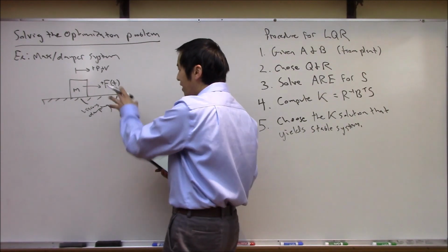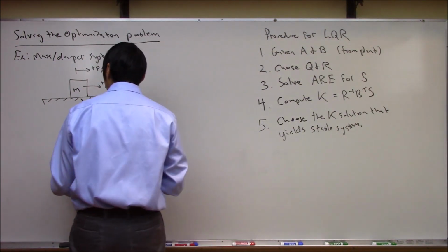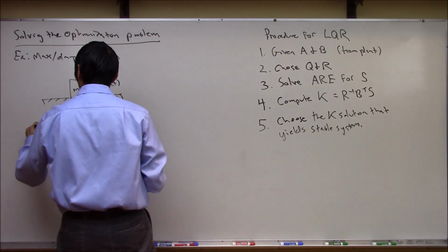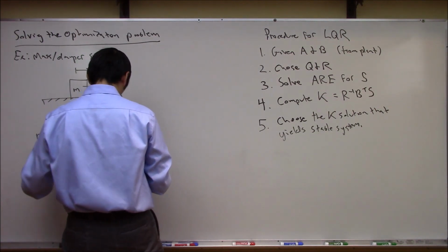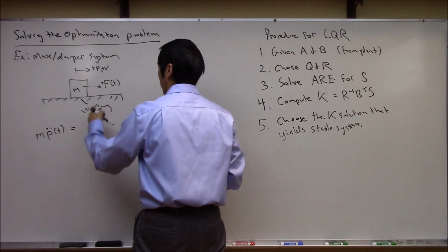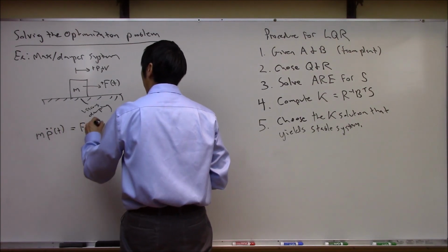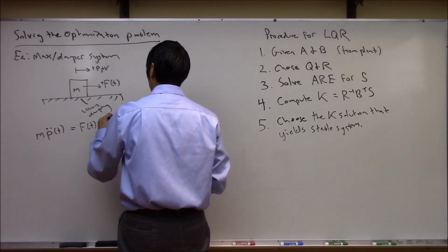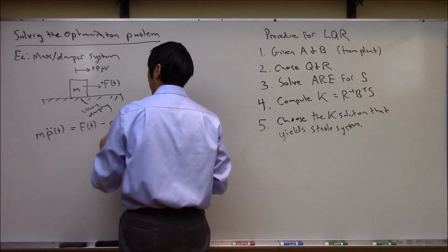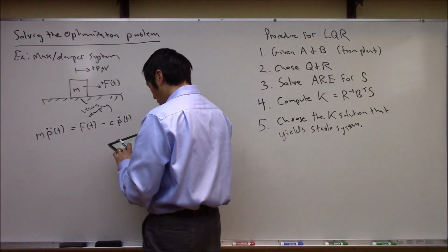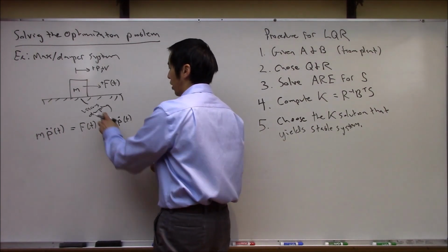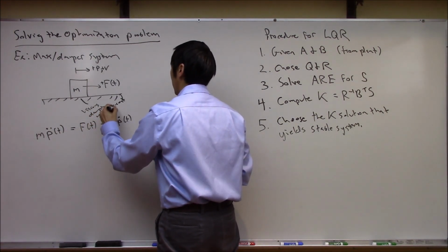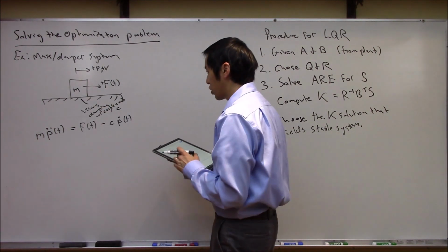All right, so I think you can get, without too much of a stretch of imagination, that Newton's second law equations of motion are going to basically give you mass times acceleration is equal to the sum of all of the forces. So you got the force here minus the retarding force of the ice, C times P dot. We should say viscous damping with coefficient C. That's what this C is here. It's just how much friction you got.